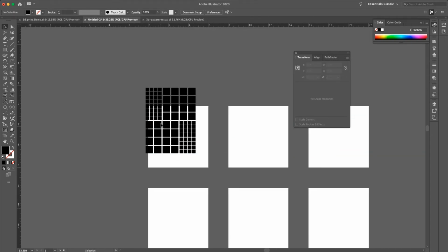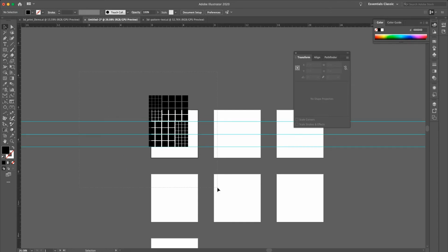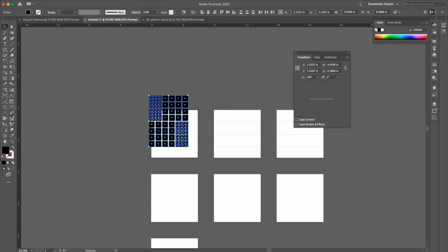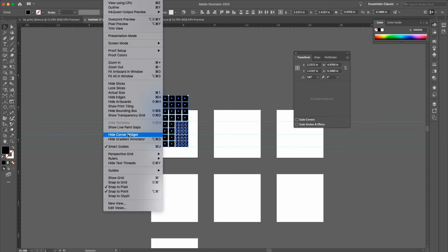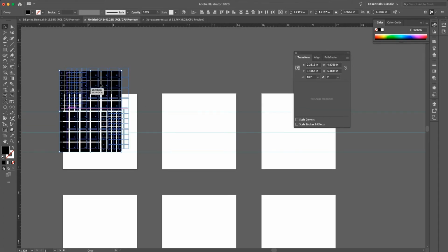Okay, and for you guys to see this, when you draw these guidelines and you highlight over them, they are locked. If you draw over this and you go to move this and it moves your grid lines, and you don't want them to move, go to View again, Guides, and then hit Lock Guides. Mine say Unlock because they're already locked, but if they're giving you trouble, it will say Lock, and that's how you can do that.